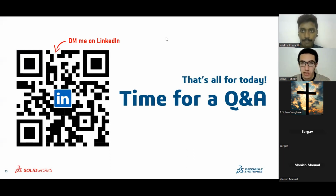Yeah, and another thing is you can create the model in a certain unit system, but when you're extracting info, you can extract the info in a different unit system, and in this case, it's going to do a conversion for you. So as I said, in the measure tool, and even in the mass properties, you can change the number of decimal places or even change the unit system. In this case, yes, it is going to convert the value for you.